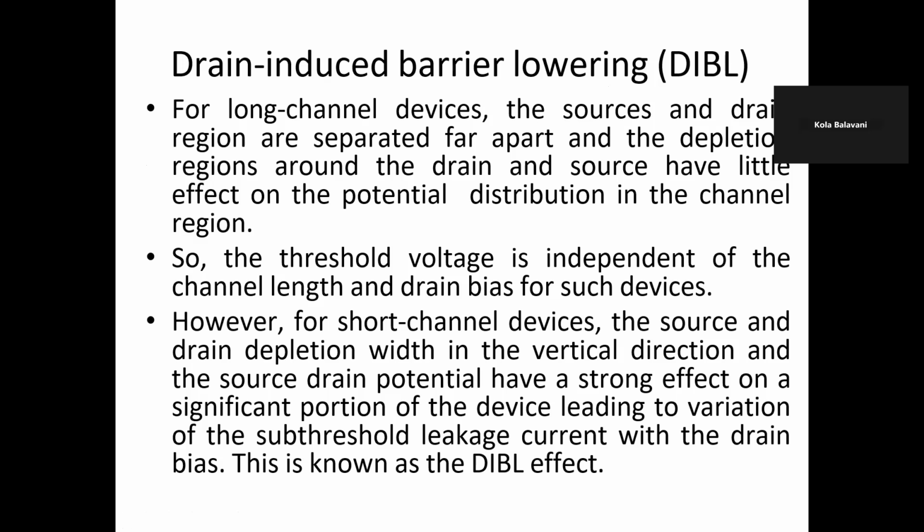So the threshold voltage is independent of the channel length and drain bias for such devices. However, for short channel devices, the distance between the source and drain is very small. That's why these are called short channel devices.